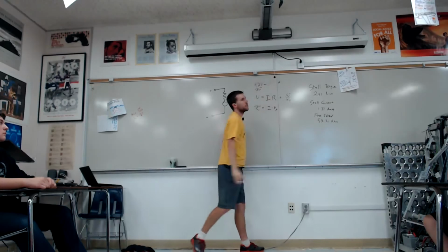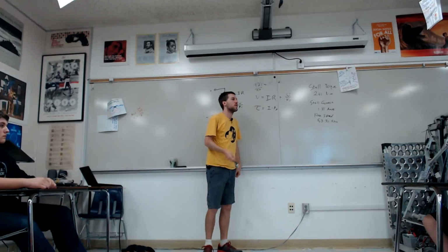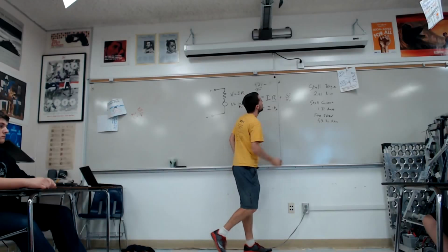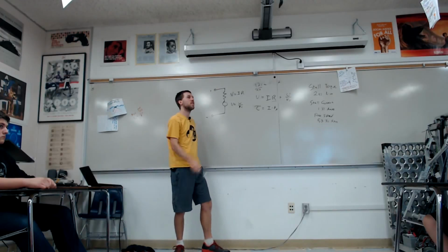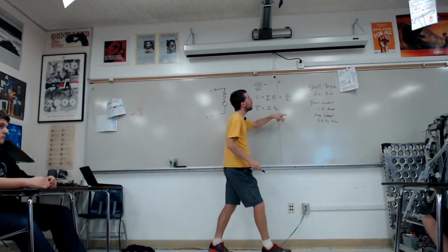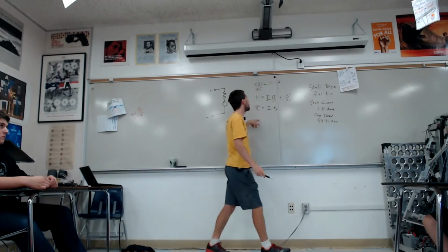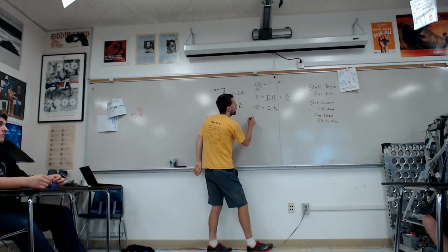So that gives us a resistance. Okay, so great, we got one of them. Can we get KV or KT? Using the second equation, can we use the stall torque and the stall current? Yep, so we got 2.41 for our stall torque, and our stall current is 131.